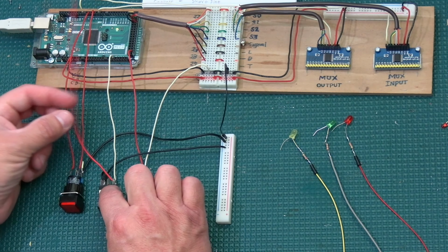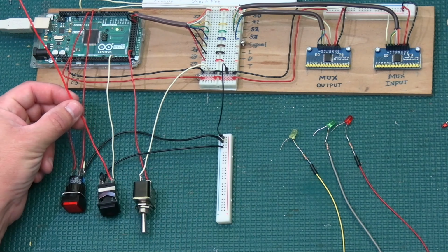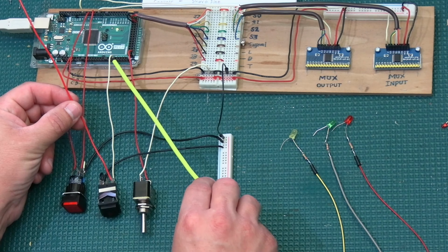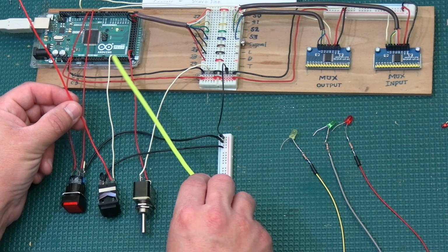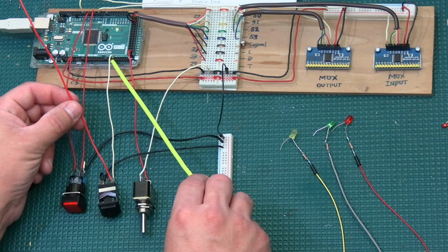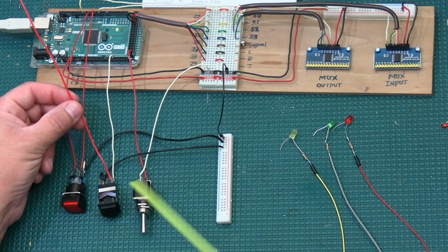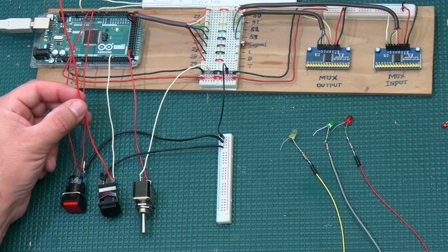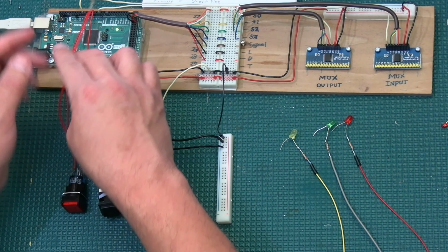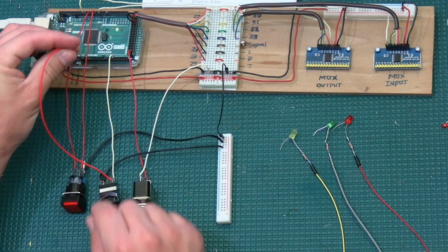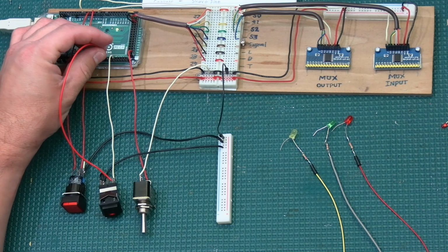Now for this one I did. So once again, the button is already connected. That one is connected to number 64 right here, which is A10, the analog ones. And then the ground is connected to the common ground over here as well. And the LED, which is this wire here that I have in my hand, is going to go to number 62 on the Arduino, which is A8. I have the resistor here at the tip just to limit the current. So I'll go ahead and put that one on A8.